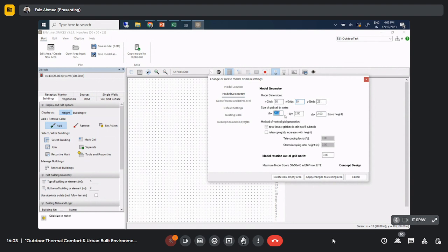This is 2 times. If you want to make more, let's say you want to scale down further, you have to scale it here, in x and y and also on the z. Ideally, like I said, leave at least 1/3 of the entire space for models. Only then we'll get a proper output. Otherwise, we'll have a lot of issues.